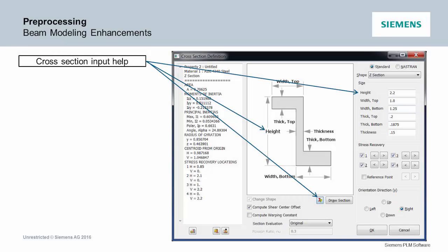Most of us have to create mid-surface models with beams as stiffeners, so we use a lot of beams. And what we did here was try to make your beam modeling and also the documentation of your beam properties a lot nicer. In Femap in the past, we always had our own standard sections. We had the standard Nastran sections, the P-beam-Ls, P-bar-Ls, and we would put up the words for what you were going to type in, but we never showed you what they really meant.